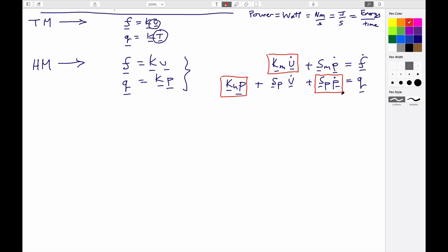And so if you increase the pressure, then the fluid would contract. It would fill up less of the volume of your element, and therefore it'd have to suck that amount of fluid in to be able to fill it up. If you drop the pressure, that fluid would expand, and it would just flow out of the system, and you'd have to release that amount out of the system. And so that's what this physical term does.